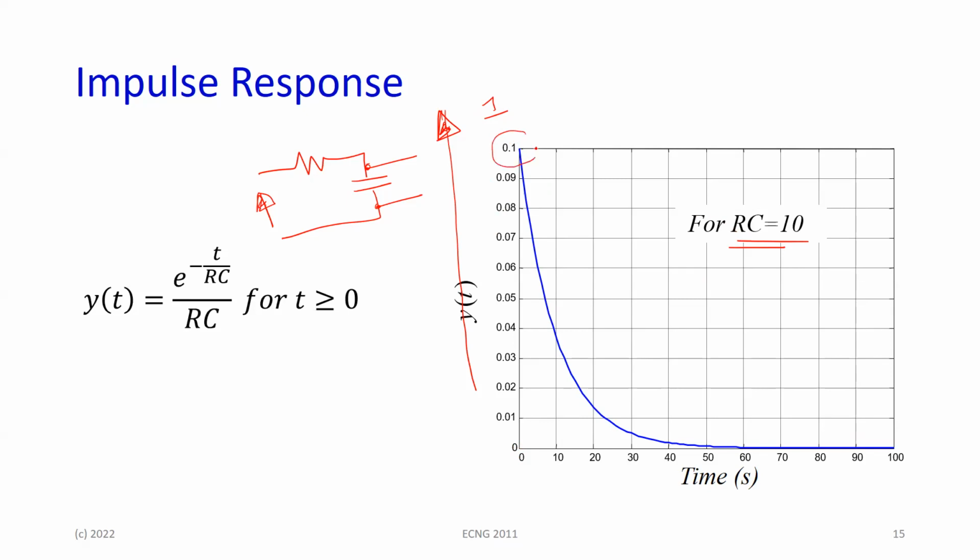The system gets up to about 1/10 of that. So the capacitor, because of the RC, obviously can't respond fully to the impulse, but it responds a little bit. So it gets up to about 0.1 volt. And by that time, the impulse is gone. Remember, the impulse is 0 time. The impulse is gone, and then the capacitor, of course, simply discharges itself again. All right.